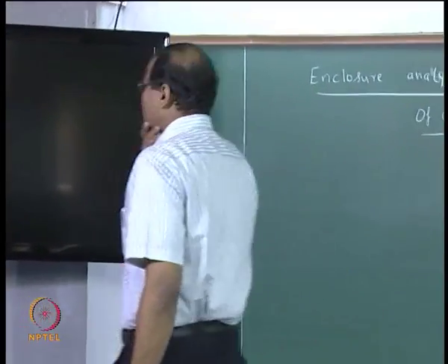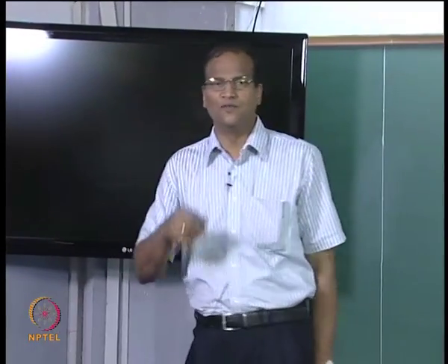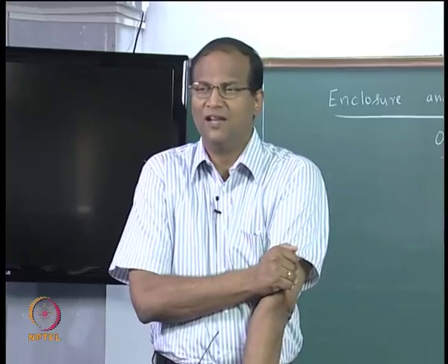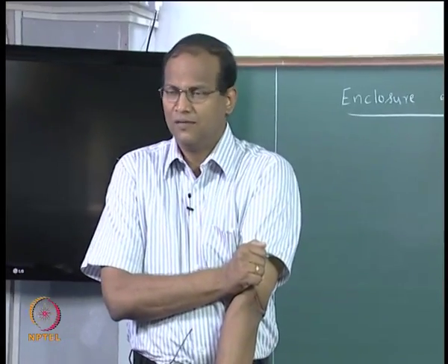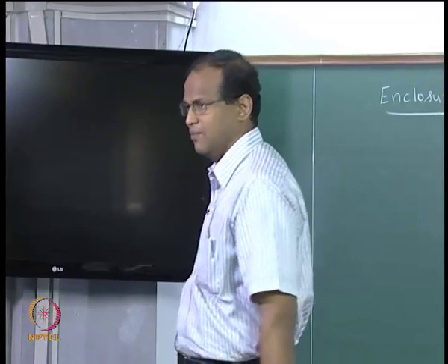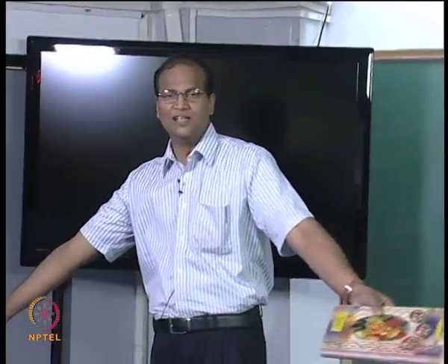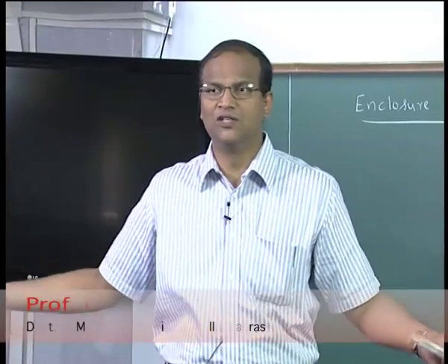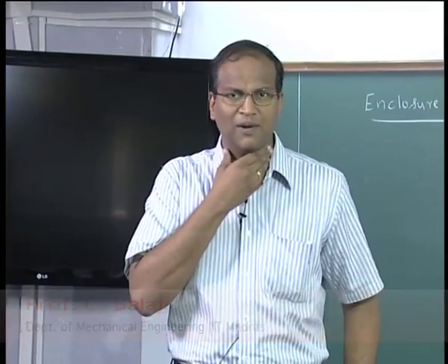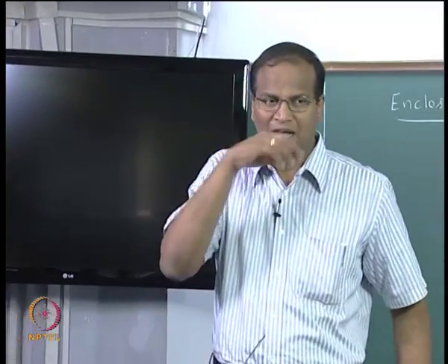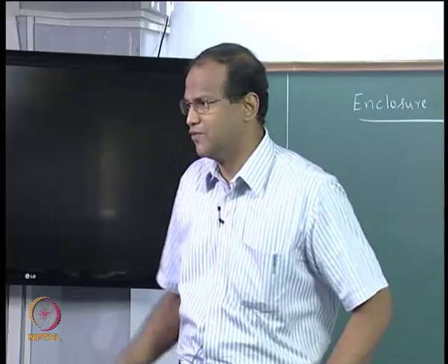So today we look at enclosure analysis in the presence of an absorbing and emitting gas. We already looked at the enclosure theory for evacuated enclosures, which is also applicable for enclosures with air or some transparent medium. Just like enclosure analysis, what you have studied can be applied to find out the radiative heat transfer between the various walls of this room. However, if you have an absorbing emitting gas, then we will have to modify some concepts of what happens to radiation in the presence of an absorbing and emitting gas.